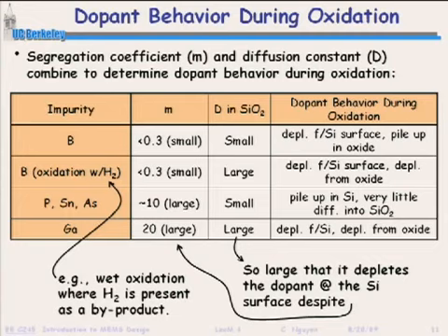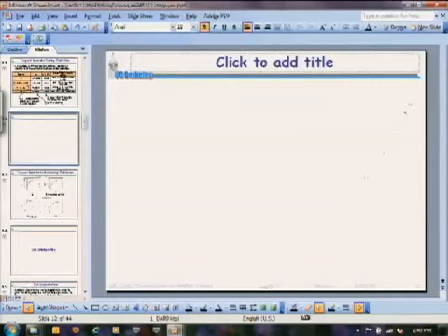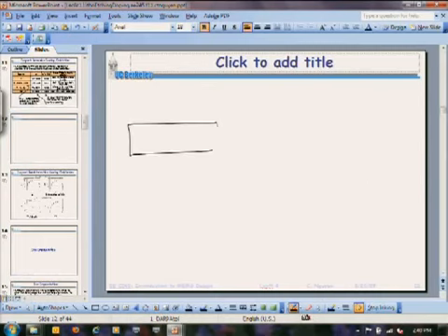All right, so say I have a silicon wafer, but it's been doped p-type. So it's all uniformly p-type. And what I want to do is grow an oxide on this. That means there's p-type material even at the top here at the surface, right? So I grow an oxide on this. And you know that when oxide grows, some of it grows into the silicon, some of it grows out of the silicon. So there's my oxide.